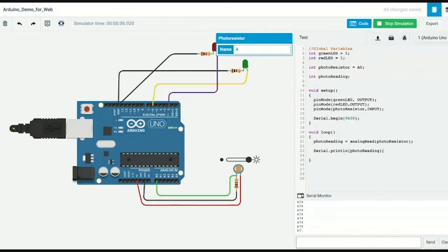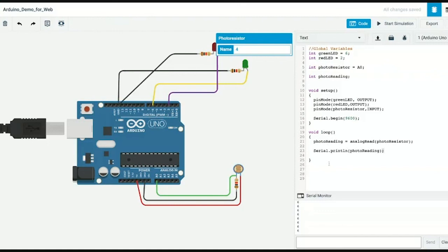We plan on using the sensor data to make decisions in our void loop. We're going to compare the data in an if statement, but we need to know what the min and max values are. Let's create a comment by typing 2 forward slashes. This will change the color of the text and allow us to write notes to ourselves. So we can see here that 6 is the min value that the sensor outputs. But what we want to know is the max value.